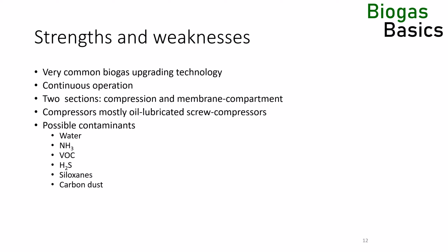All compressors, even oil-free reciprocating compressors, leak some oil droplets and oil vapor into the biogas and require an oil removal step with a small activated carbon filtration. Downstream of the oil removal carbon should be dust filters to capture carbon dust.